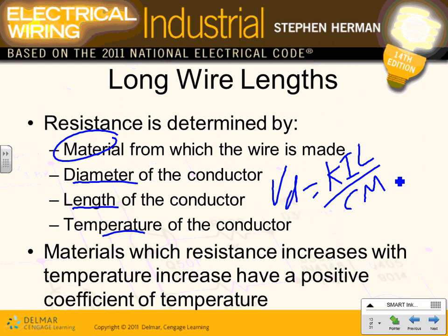Well, a lot of engineers actually run a voltage drop calculation on the load anyway. It's not hard. For branch circuits or feeders, you take the full load amps. So if you have a panel, a three-phase voltage drop equals 1.73 times K times I times L divided by circular mil. So I is 100 amps.